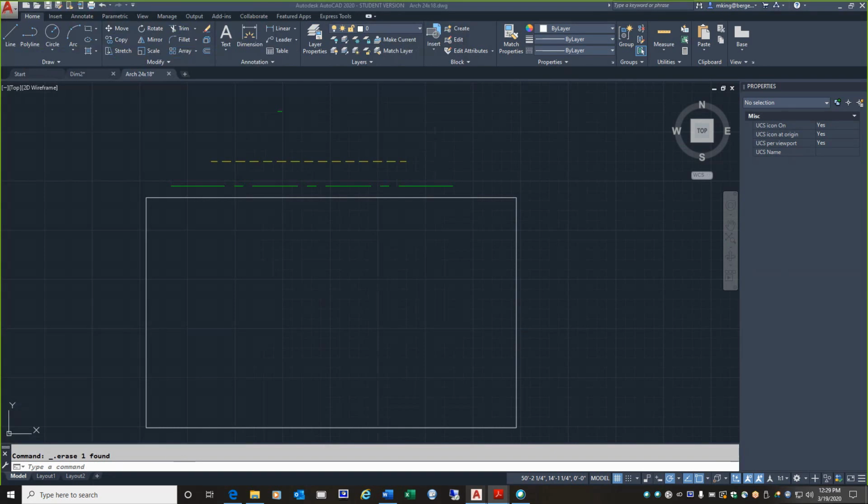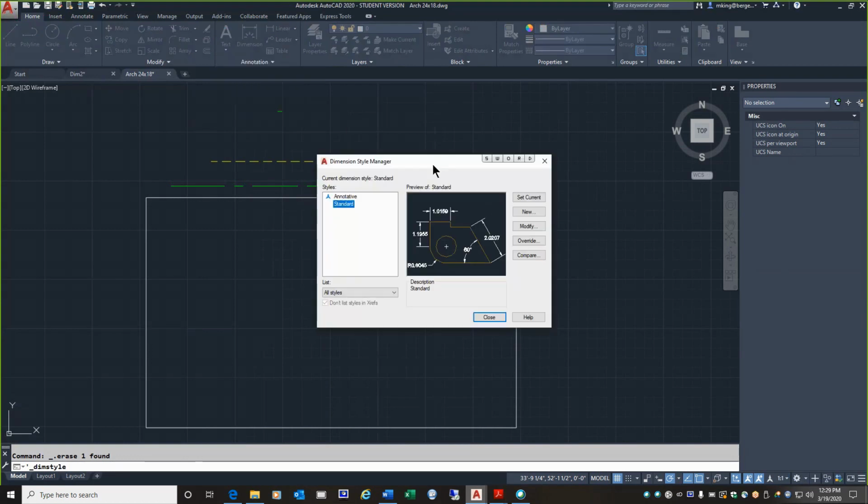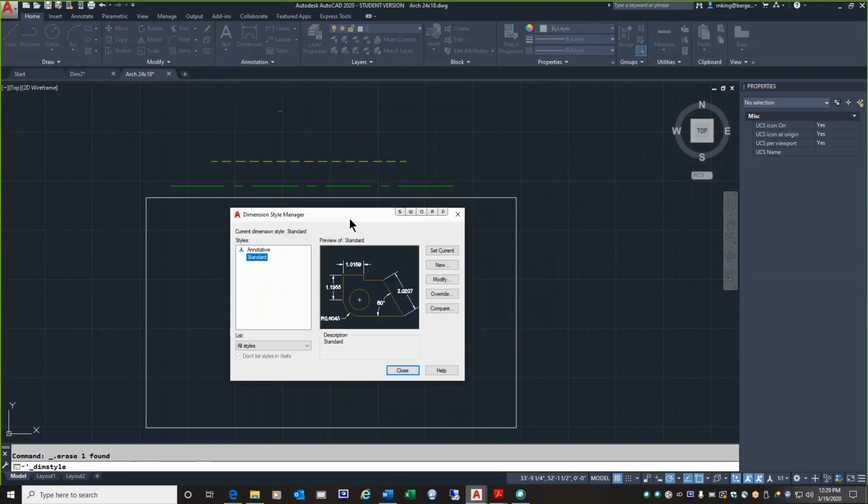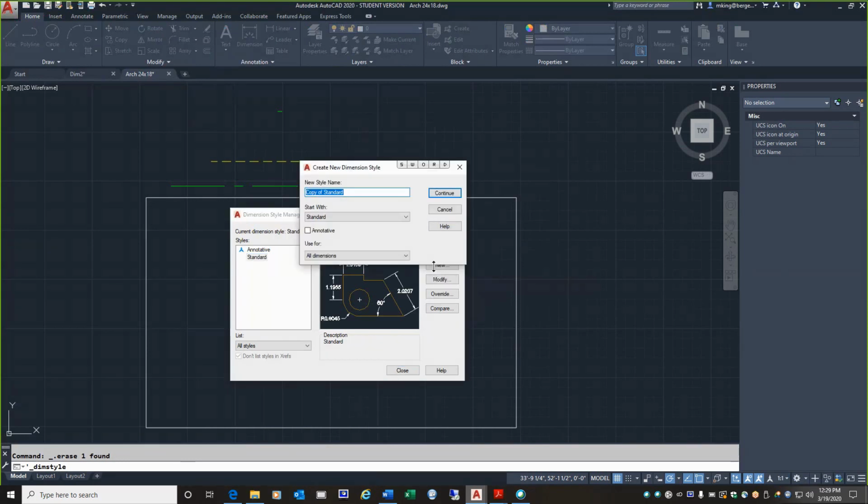All right, so with this in mind, in this drawing, since I'm in the Home tab, I'm going to go back to the regular way. I'm going to go to Annotation and my Dimension Style button, my Dimension Style Manager, and New. Okay, so this is step 2. Dimension Style button, New. Now, if you look at the booklet, the name I'm recommending is